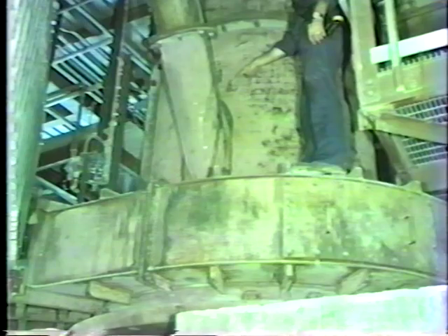Now with the door replaced and bolted tight, the mill is brought up to 92% load, and we can now see the raw coal feed through the viewport. The coal contains 7% moisture and has 13,000 BTUs per pound. The raw coal drops down the stainless steel feed pipe into the pulverizer. Control of the coal feed rate is by the Williams microcomputer, which sets the feeder rate to exactly match the boiler demand signal. Coming down and into the mill.